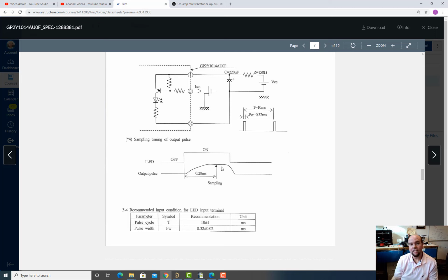And we don't want this thing to save the peak forever, though. We want to pulse this thing periodically and get these peaks, but over time we want the ability for that signal to drop back down. If the air quality gets good and the voltage drops, we need it to actually reflect that. We can't just keep a capacitor charged forever, because then the worst-case air quality would forever be the air quality that it's measuring. No, we want some time constant to let it dissipate.